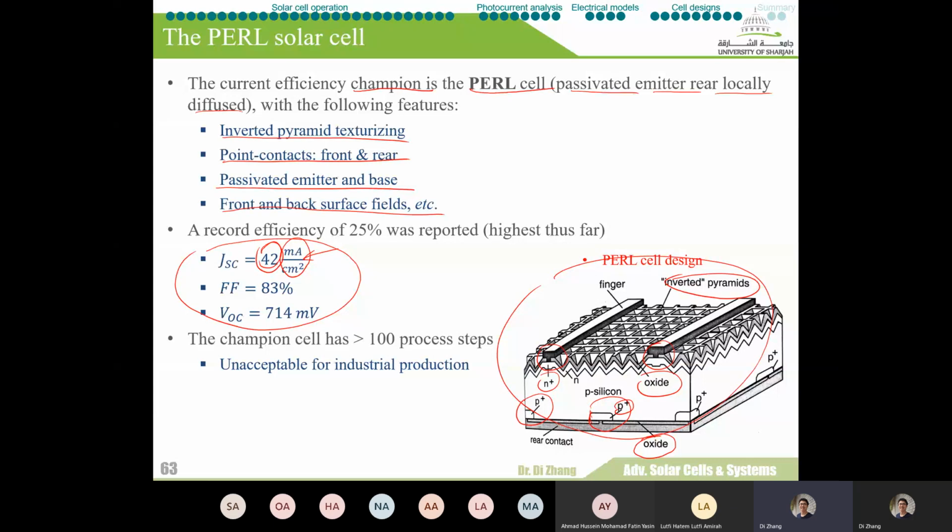And then depending on your solar cell material, for instance, as far as I know, for third generation, we typically have a lower performance. For organic solar cells, typically the JSC is in the range of maybe 10 to 20 milliamp per centimeter squared.